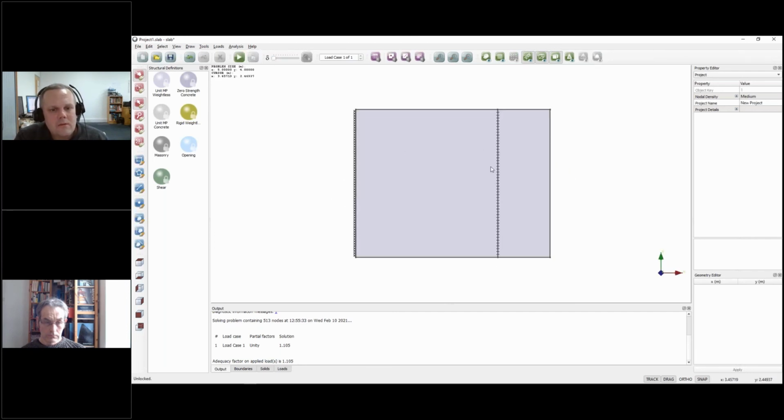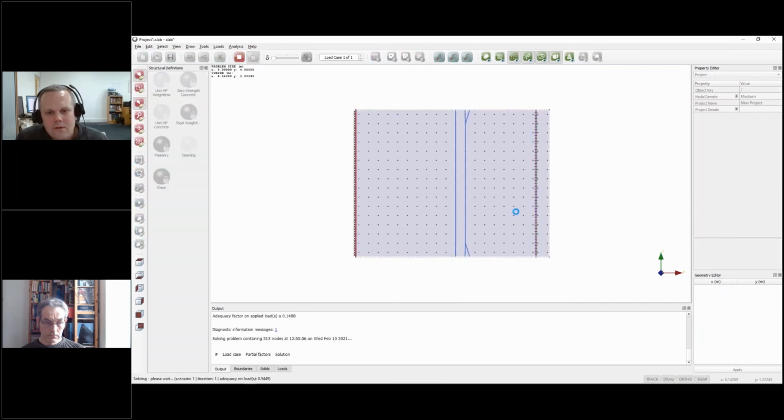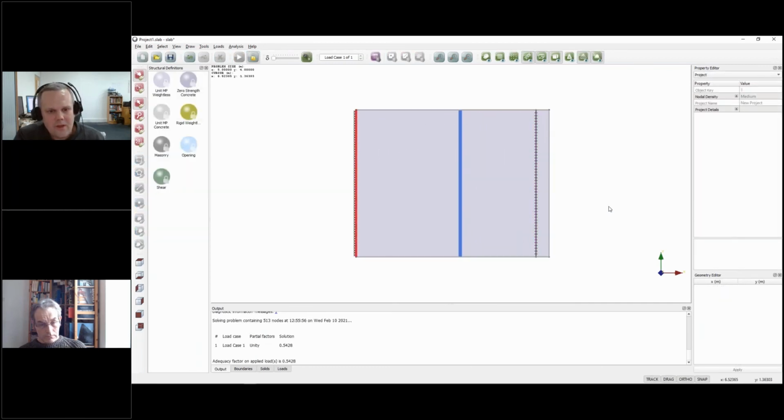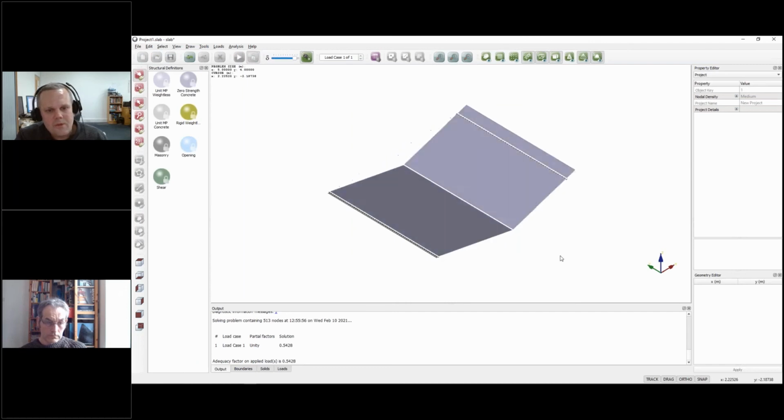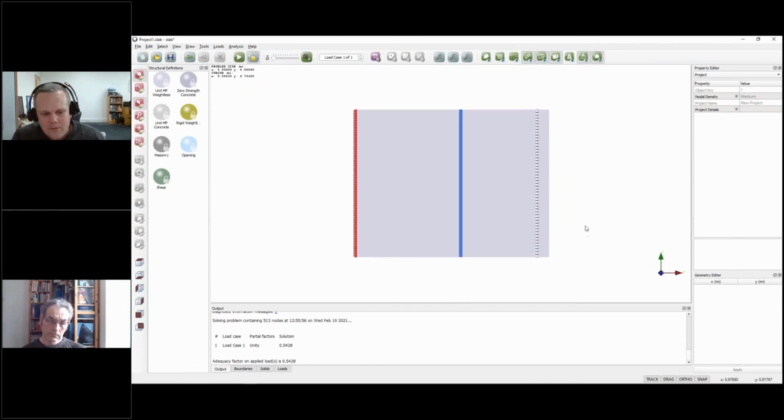but you can very easily, if you want, if I turn on ortho, you can move that line to different places. That's obviously going to be there, but if I move it maybe further that way, see what happens. Yeah, you can see it here, we get the sort of folding book type failure mechanism. So yeah, continuous slabs over knife edge supports are not a problem.